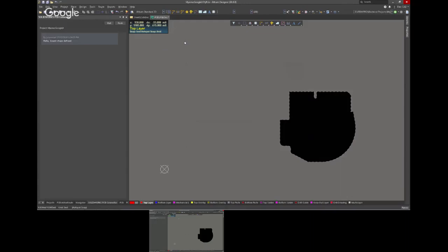This takes us up to 5 minutes. And again, I've been using Altium for 12 years. It takes me 5 minutes to get just the DXF, and I have the video and I can play it and it shows side by side. 5 minutes just to get the DXF, reposition it, define the board shape, put the dimension, make sure. Because again, when we receive a DXF, just for those who do not know, we have to deal with scaling and units. I do not know what the scale and I do not know the units, so it's a trial and error until I get it right.